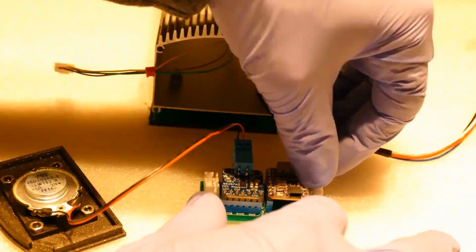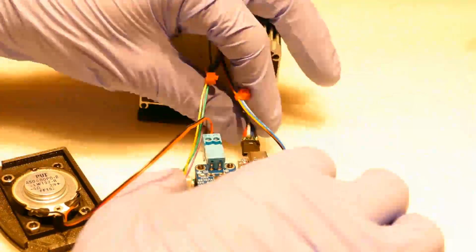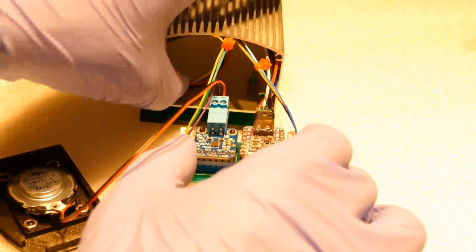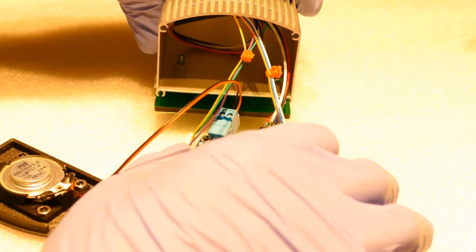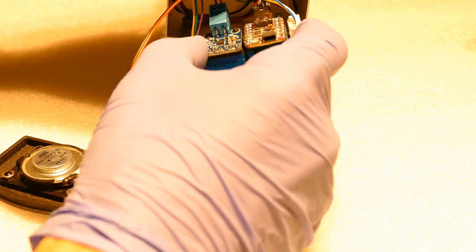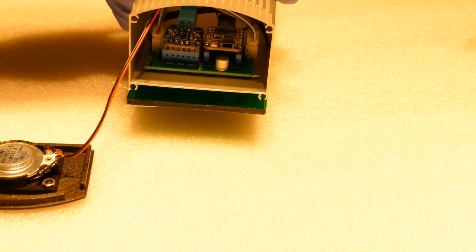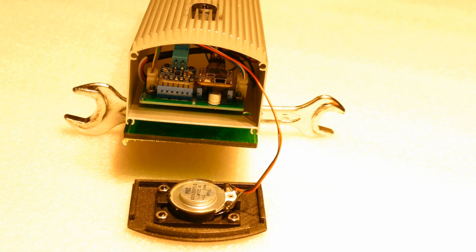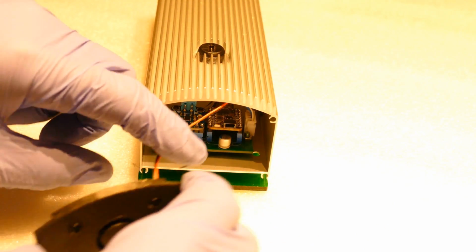The 2 OLED plugs are plugged into my custom PCB. The USB plug is plugged into the QT Py. The screws on the side of the case will also hold the custom PCB in place. M3 by 3mm PVC spacers are placed on the screws to hold them in place and to ensure the bottom of the PCB doesn't short out on the aluminum case. Off camera, I added M3 nuts which keep everything together. That takes care of all the hardware.